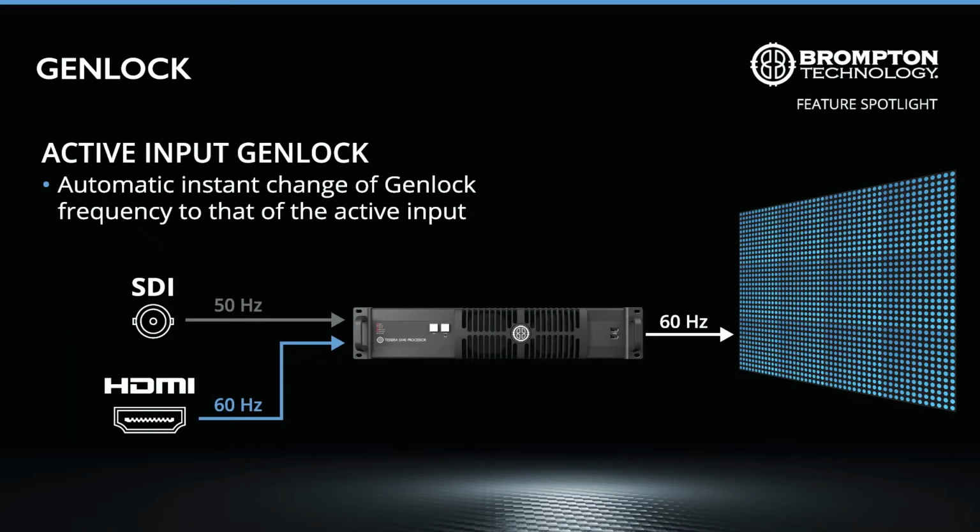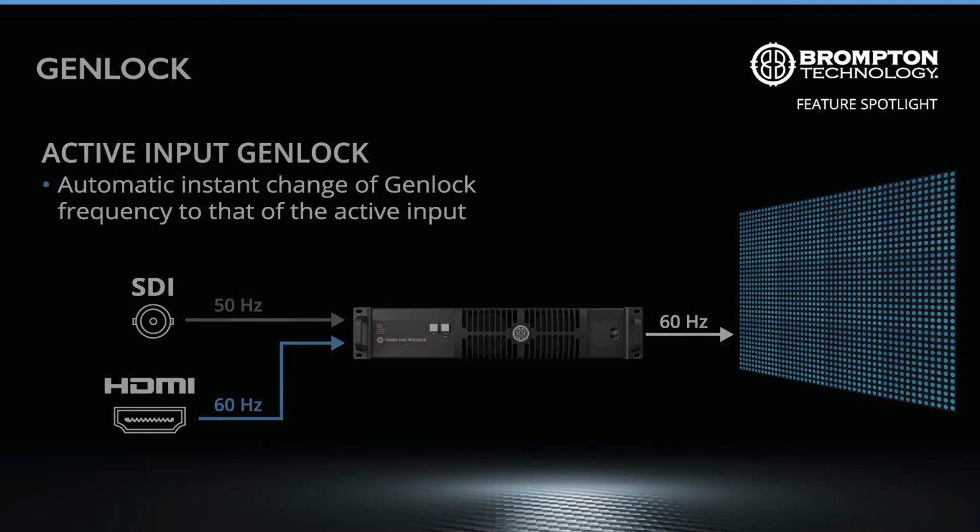The active input feature is available for the Tessera SX40 and S8 LED processors from Tessera version 2.3 onwards. This allows automatic and instantaneous switching of the Genlock rate based on which video input is being used as active between the HDMI and SDI ports.